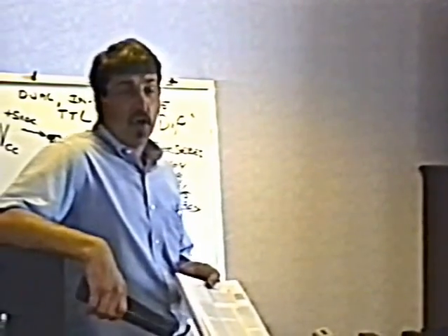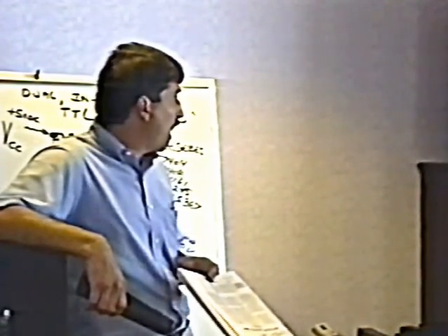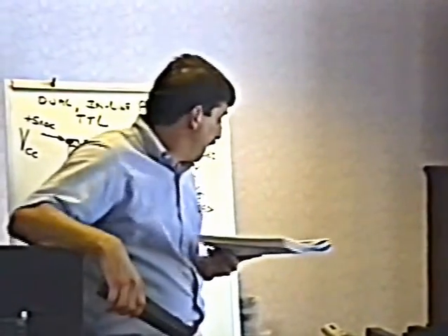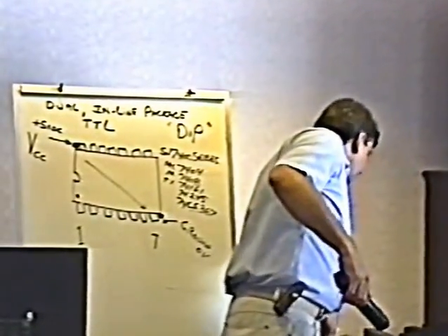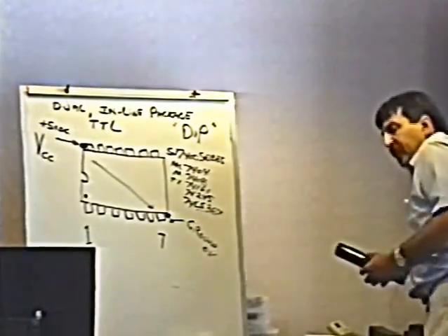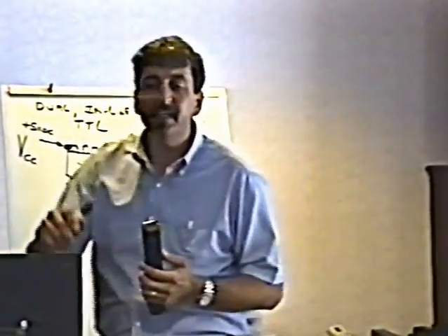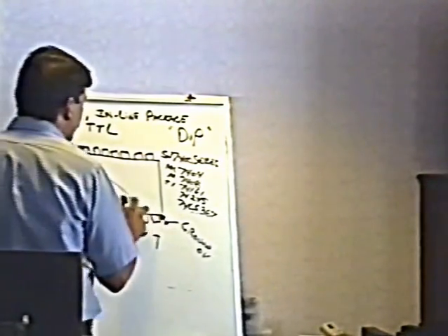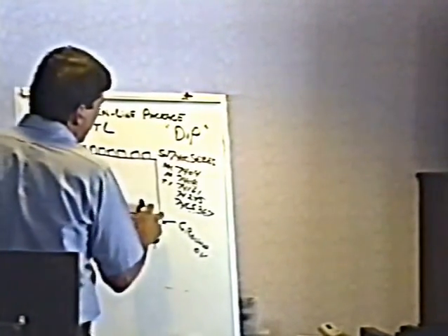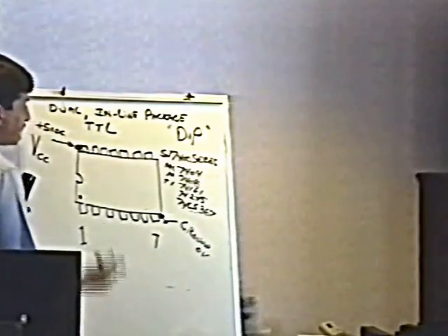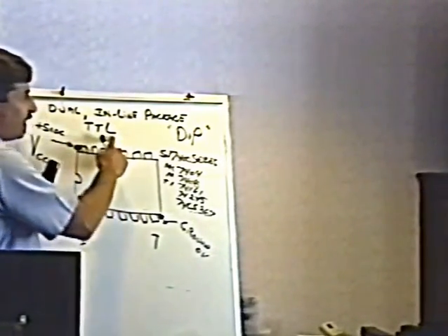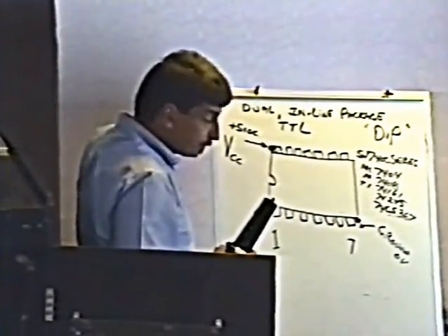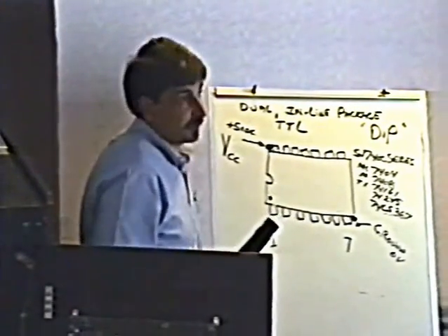What I'm about to show you is something that I'll discuss again when we talk about pinball machines. But what I'm about to show you is a little trick that will enable you to find bad integrated circuits on logic boards without even knowing what the hell you're doing. And it's based on the fact that these integrated circuits are TTL, transistor-transistor logic. They're made of transistors inside.